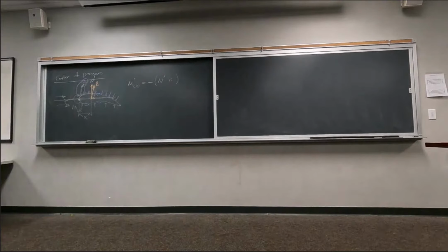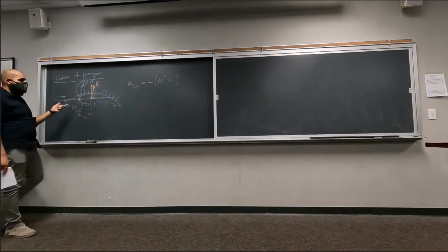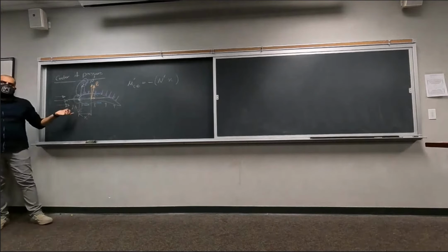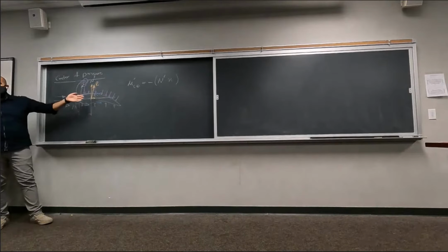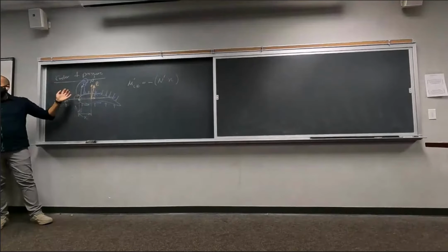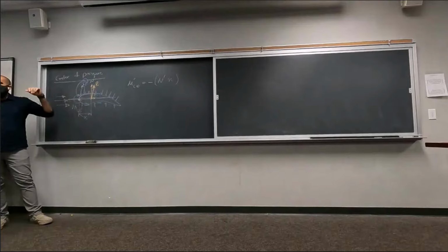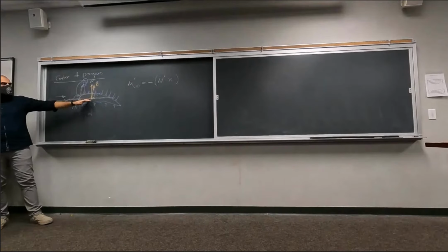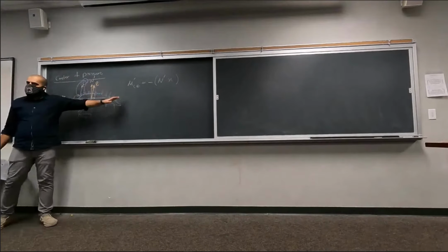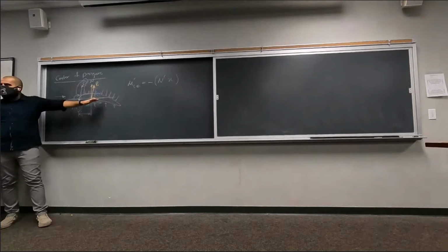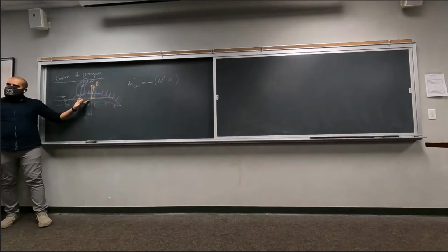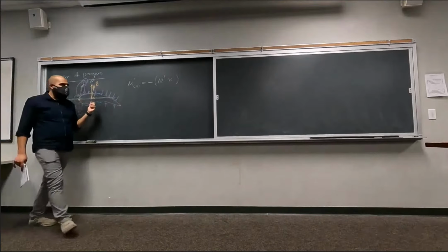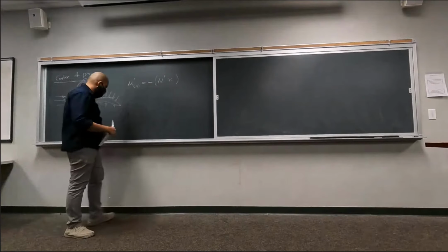So, as long as we can calculate the moment on the leading edge, we should be able to find a point inside or outside of this object that exerts the same moment on the leading edge as the pressures and the shears on the object, right? And that distance is going to be called the center of pressure.